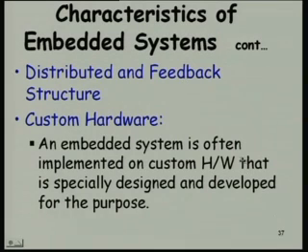So, we have different kinds of embedded processors. For example, ARM processors are an important category of embedded processors, but you will see that we do not use a general purpose board or general purpose hardware many times, just for cost consideration, size consideration, and specific characteristics. We need only a specific part of the processor. So, why do we invest in a full processor? So, these are some of the reasons why many of these are based on custom hardware.